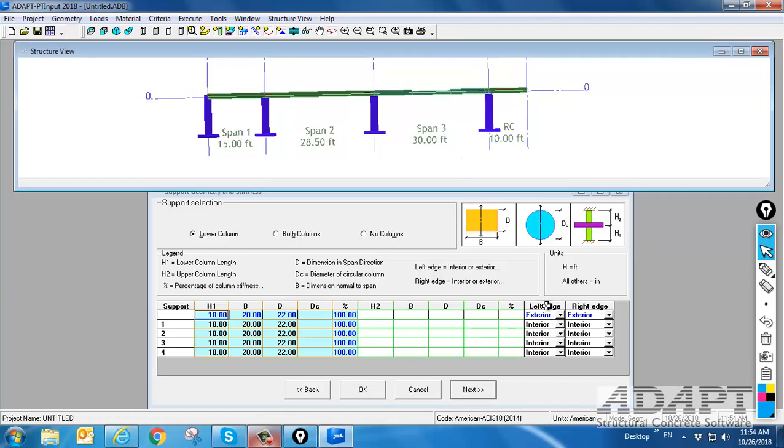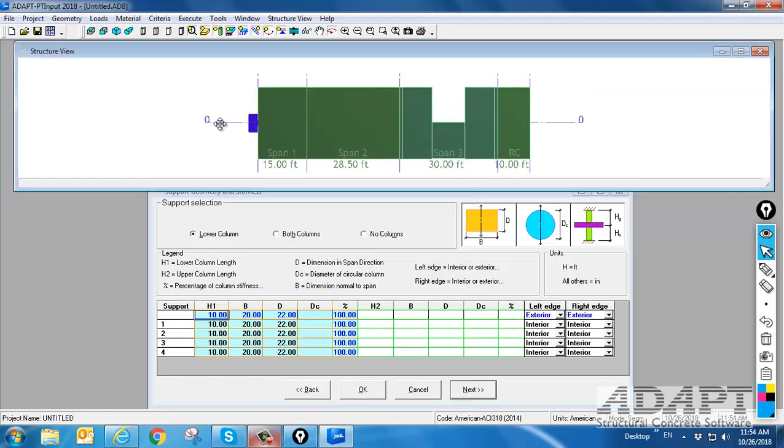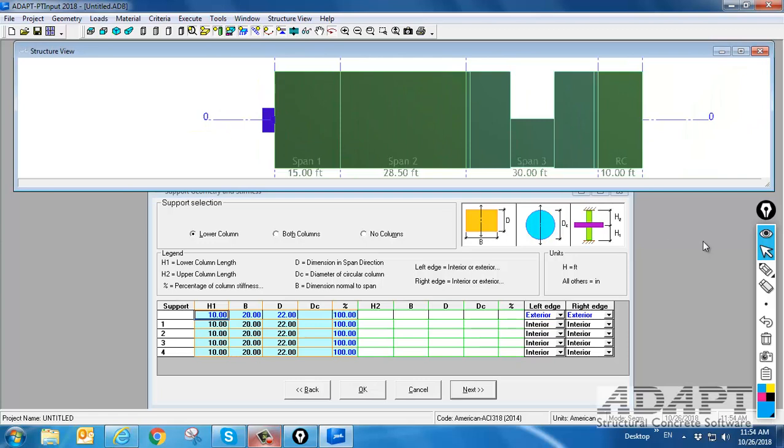Okay, the left and right edge, I'll go back to the plan view. Again, remember that this is the left and this is the right. So for 2A slabs, we typically check punching shear at some critical sections away from our columns. I'll just draw some rectilinear critical sections here. These might be the first critical sections that we check at some distance d/2 away from the face of the column.